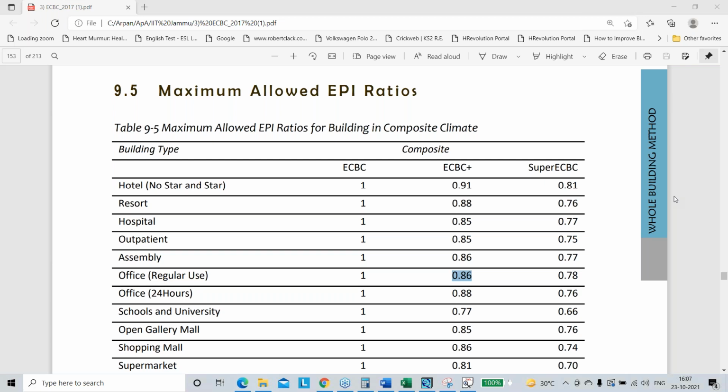so that exact volume is used for the cooling load calculations. So whenever you are inputting the floor to ceiling height, in that case you have to just consider the height up till which cooling will happen. So if there is a false ceiling, then just take it to that level, because your HVAC load will be sized for cooling up till that height only.